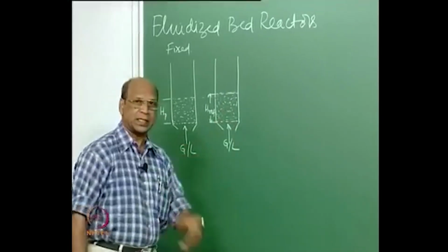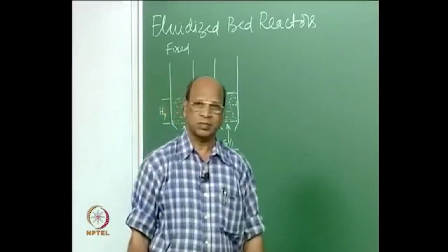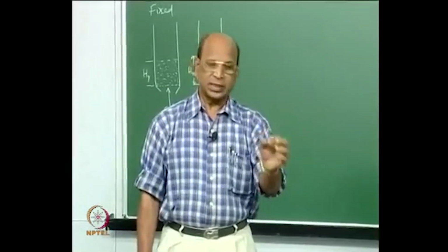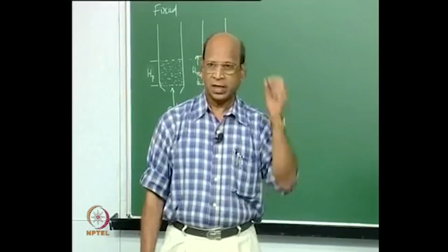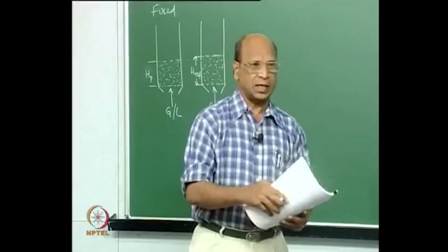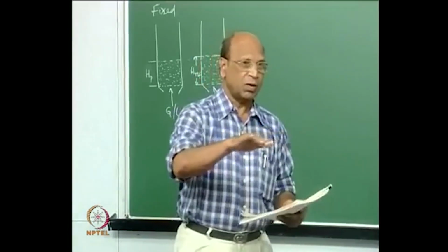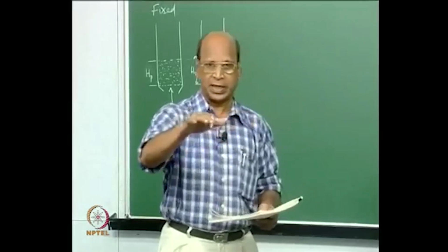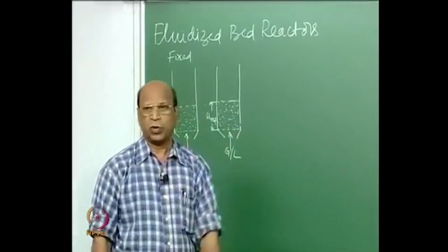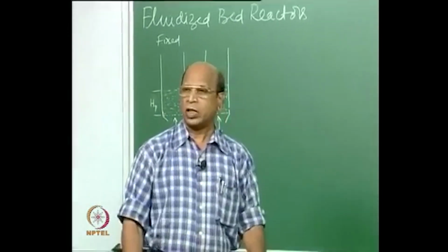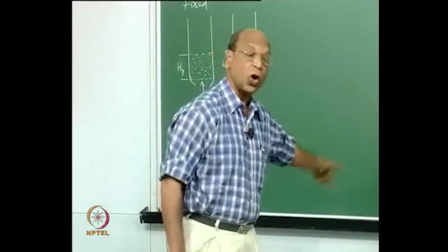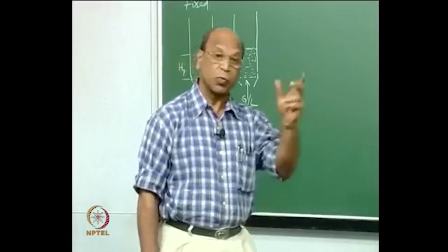So, then we made it a fluid where it can easily move. It acquired all the fluid properties, like density difference: something can sink and something can float. When you change the direction to any inclined position, all fluids still maintain a horizontal surface. The same thing is there, and if you put a small hole, it will come out like a fluid. All the properties we normally see for fluids are seen for solids in the presence of another fluid.